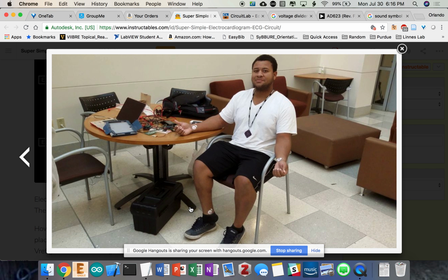There are some techniques where you can do 1 electrode, but because you don't have the subtraction of the 60 hertz noise, it will often be a little more noisy, but it is possible in some contexts, and useful. With the 12 lead ECG, where they put 12 electrodes all around your chest, some of those electrodes are actually single-ended, so it's not differential, it's just a single point measurement. And that has different diagnostic value than differential measurements.